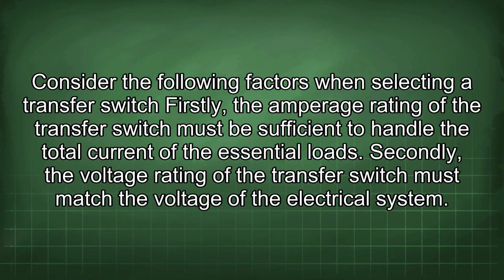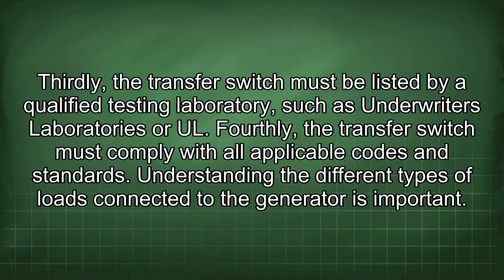Consider the following factors when selecting a transfer switch. Firstly, the amperage rating of the transfer switch must be sufficient to handle the total current of the essential loads. Secondly, the voltage rating of the transfer switch must match the voltage of the electrical system. Thirdly, the transfer switch must be listed by a qualified testing laboratory, such as Underwriters Laboratories or UL. Fourthly, the transfer switch must comply with all applicable codes and standards.